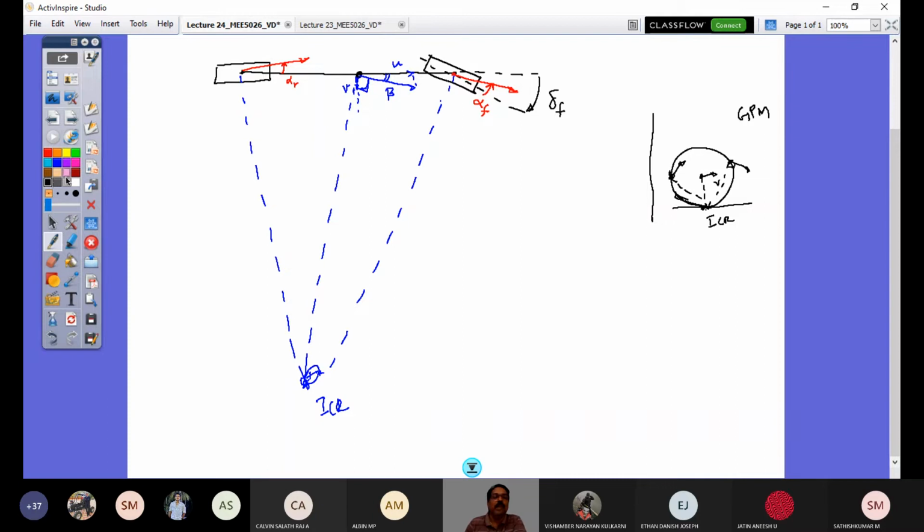So now what are the forces going to act? So see, now I would have, as it is turning in a steady state cornering, I would have here a force, and this force is Fy F, and this force is Fy R. And these are the forces developed, and as it is a dynamic equilibrium, I would have my inertia vector, and that inertia vector would act in this direction. What direction it would act? At the CG, in this direction it will act.